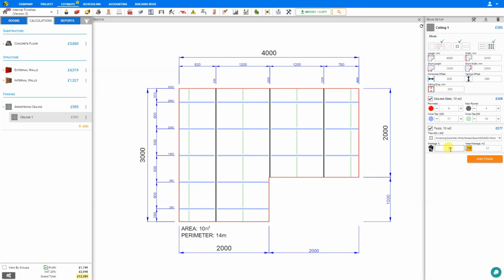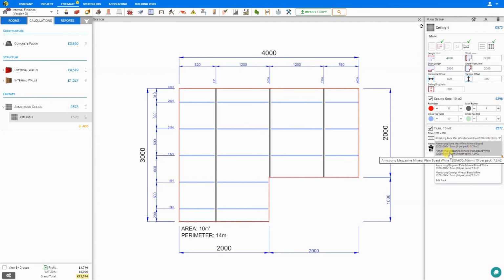And you can see with a 20% wastage that 12 square meters will be required to cover an area of 10. Now all these quantities have been calculated using a square tile, and these are 600 millimeters square. However, if we choose, we can also opt for a rectangular tile, which is double wide, 600 millimeters by 1200 millimeters. And when we do so, all the 600 millimeter cross T's are reduced to 0 and removed from our sketch pane. And our tile selection now changes to an assortment of 1200 by 600 millimeter tiles.